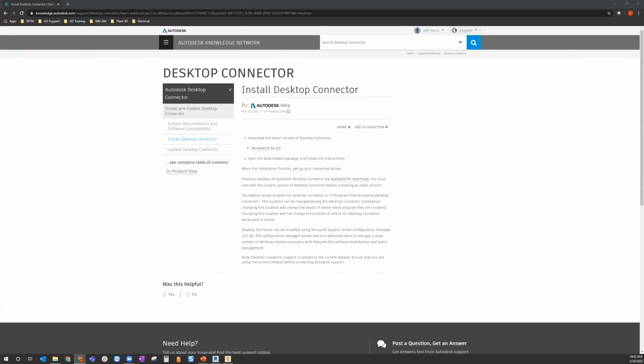Yeah, so just to clarify, the only difference I did on there was I believe I exported it so that I could utilize the part for Plant 3D. So the only difference you're going to do is you're just going to change your save as to an RFA file if you need it for Revit. And that should be the only difference. The whole process and workflow should be the same, so you could simplify these models for preparation inside of Revit.